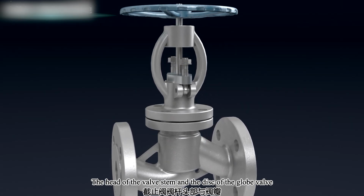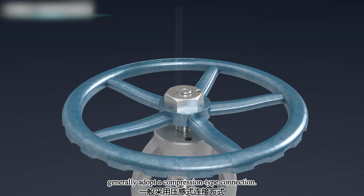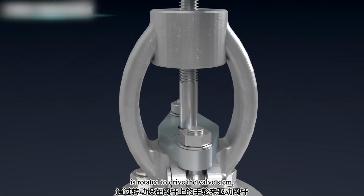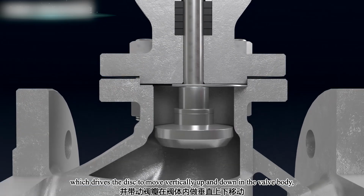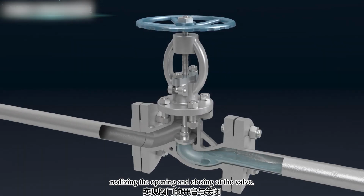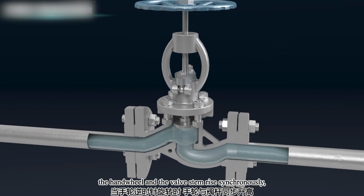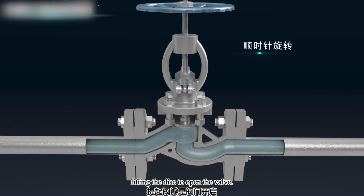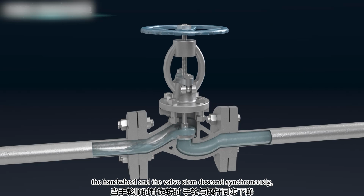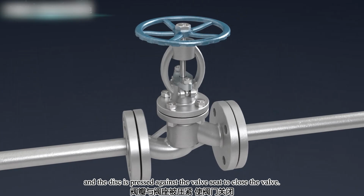The head of the valve stem and the disc of the globe valve generally adopt a compression-type connection. The hand wheel set on the valve stem is rotated to drive the valve stem, which drives the disc to move vertically up and down in the valve body, realizing the opening and closing of the valve. When the hand wheel rotates counterclockwise, the hand wheel and the valve stem rise synchronously, lifting the disc to open the valve. When the hand wheel rotates clockwise, the hand wheel and the valve stem descend synchronously, and the disc is pressed against the valve seat to close the valve.